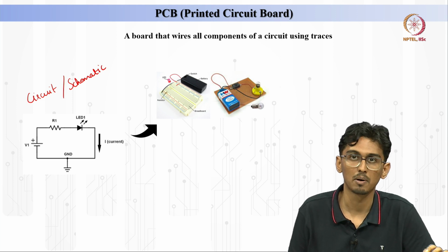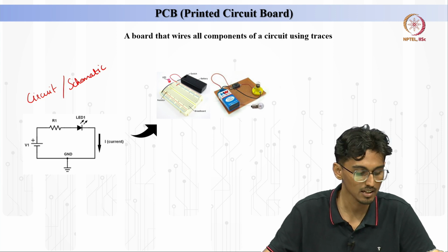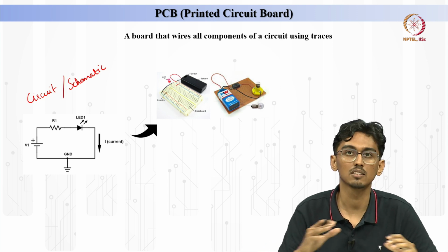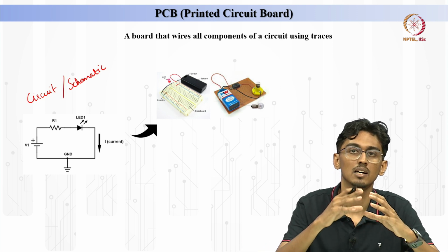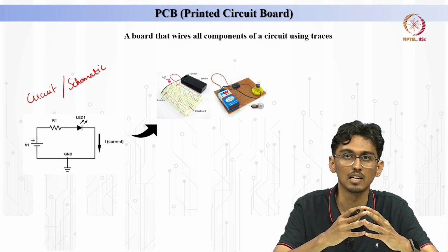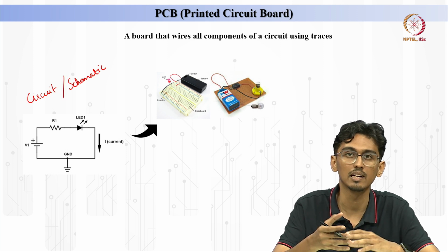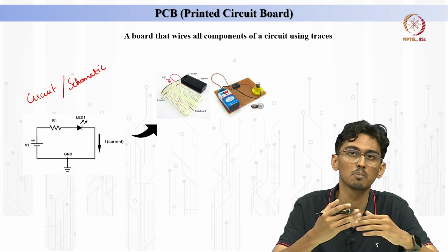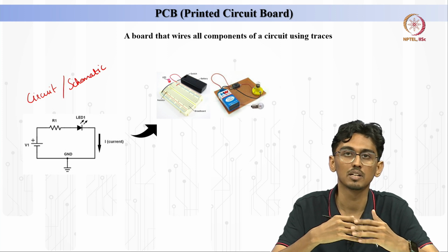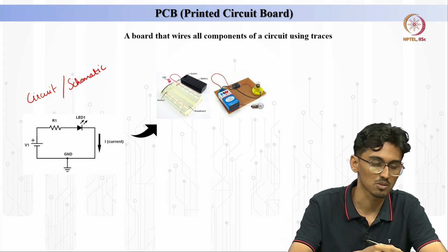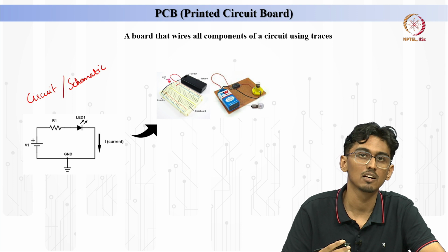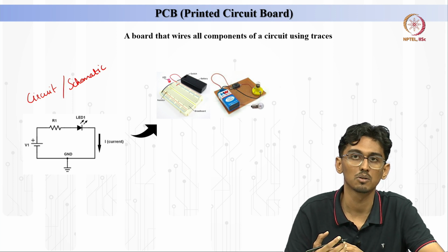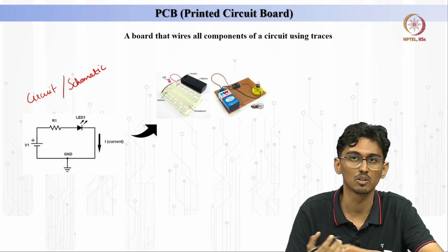Here I have a power source to actually illuminate the LED, and I have to make sure that this power source conforms to the requirements of the LED. It should not be too high, so that the LED heats up and fuses, or too low, otherwise the illumination never occurs. Now that is one thing we consider, and then we include some form of resistance in order to control the current that needs to go into the LED.